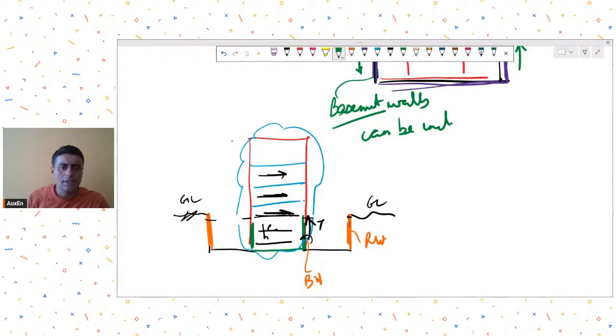In this condition, because it's unconnected with any horizontal system, you take the full height for time period calculation. So for time period calculation, your code puts this thing, but your statement that basement walls will not take base shear is an improper statement. We do consider the effect of basement walls or underground walls in resisting base shears and overturning moments also. So this was his question.